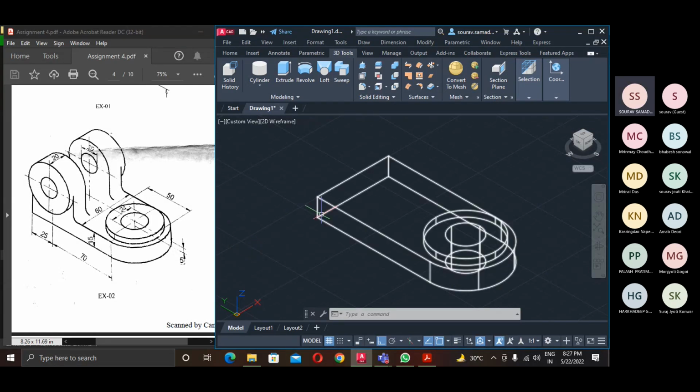Now you need to construct a box on this face. So here one option will be very beneficial, that's called DUCS. What is this DUCS? That's called dynamic UCS system. And what is the function key that invokes the DUCS? That is F6. Choose the F6 option. See, the dynamic UCS option will be on. What is the function of dynamic UCS?